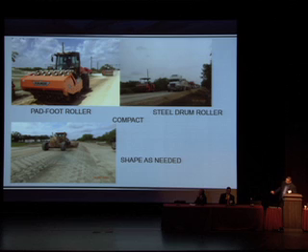Again, once the rollers are done, you can immediately shape the layer. One thing that stood out in my eyes is when we started shaping the layer, the blade actually cut the larger aggregate in half because it was so bound. The fines had welded the larger aggregate in place, and it was shearing the larger aggregate in half.